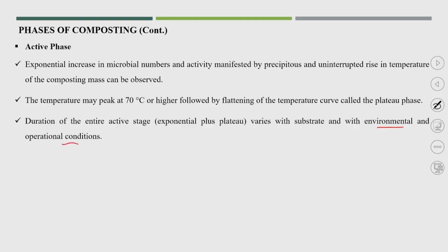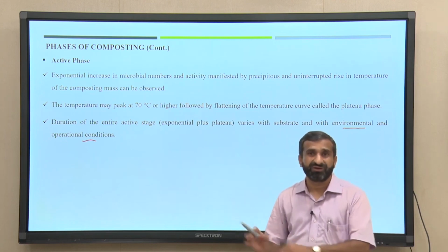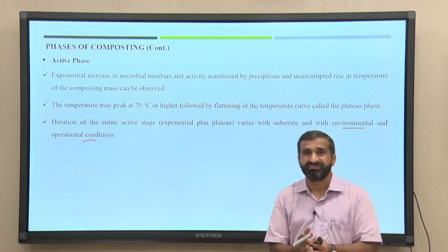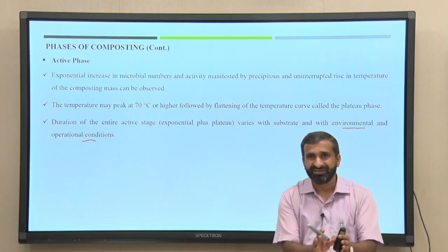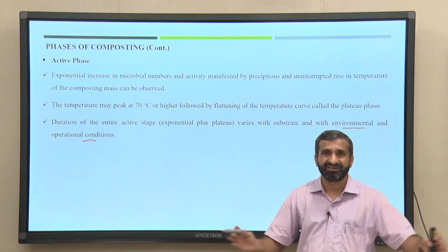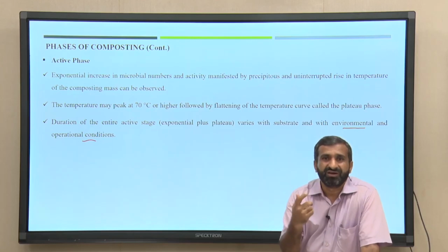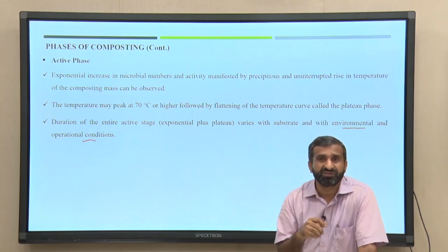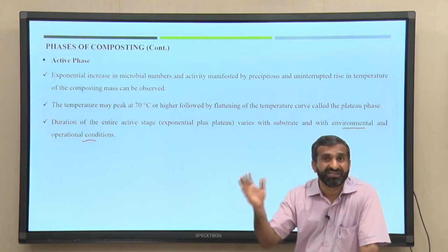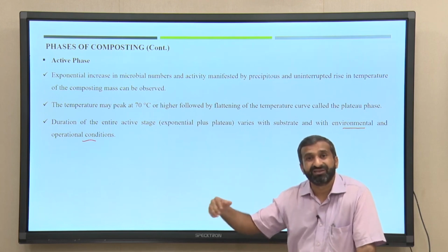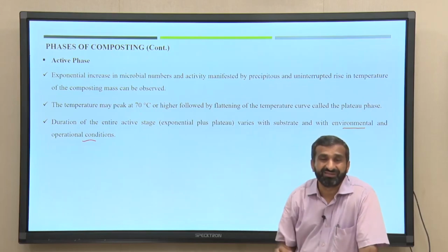Many times it is believed that composting is possible only under proper ambient conditions. So, what could be the proper ambient condition? It means no rain and a temperature of 25 or 30 degrees, but that is not possible throughout the entire year. Earlier, we did not know much about the composting process, and we believed that composting won't be possible in the rainy season, or when the ambient temperature is 10 degrees in December and January. None of the composting plants used to be run in those periods.